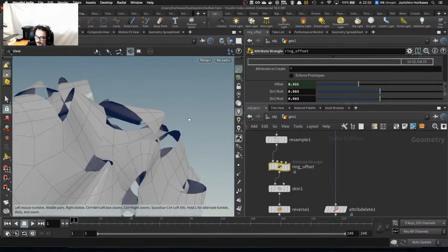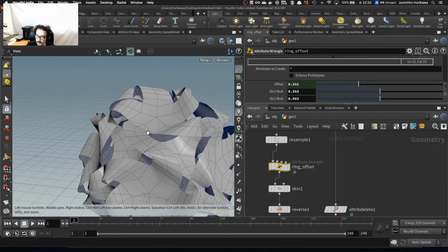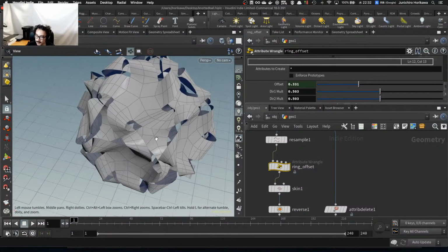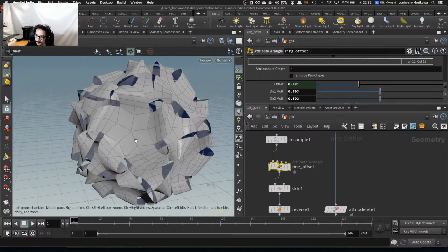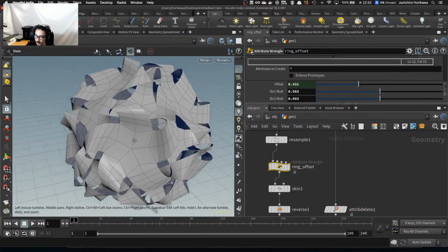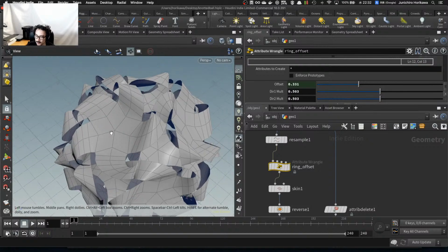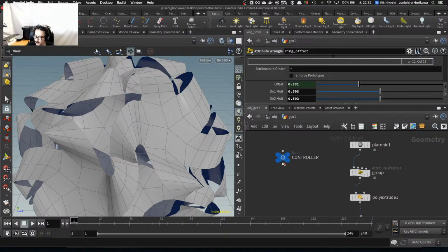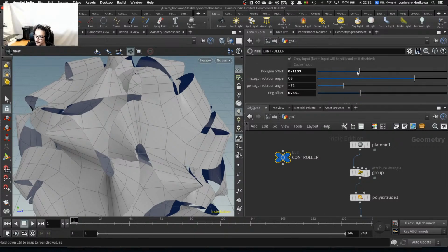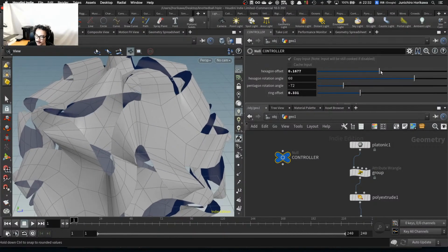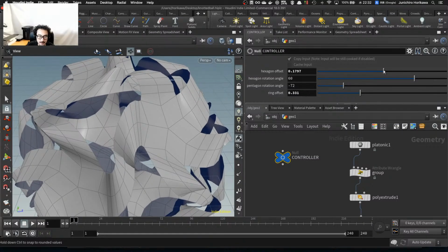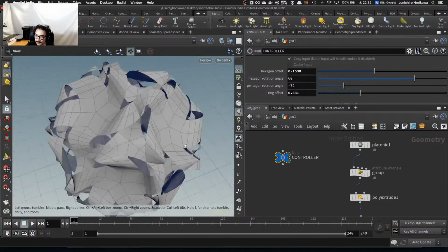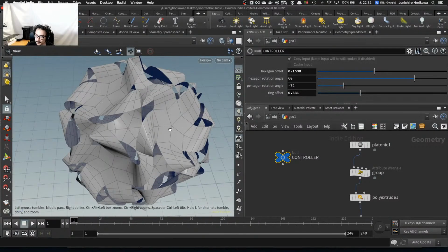So to have more coordination, to have more control over the final shape, let's have some additional parameters in order to control those shapes. Now one thing I could control is the size of the pentagon and the size of the hexagon, and I am already able to control the size of the hexagon by changing this hexagon offset, as you can see like this. But right now the size of the pentagon is fixed. There's no way to control that. So let's add a new parameter in order to control the size of the pentagon right here.